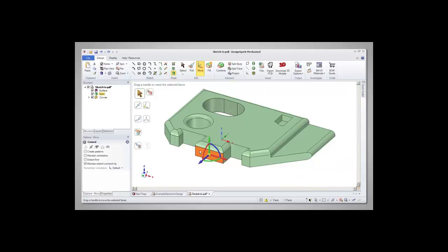The curved arrows on the move anchor enable rotary adjustment of a feature. The same 3 steps apply as before. Select the feature, select the direction of rotation, and finally rotate it, either by dragging the anchor or by typing in an angle.